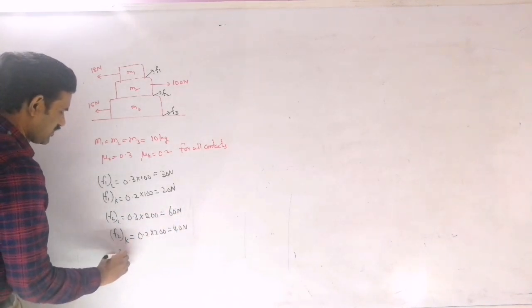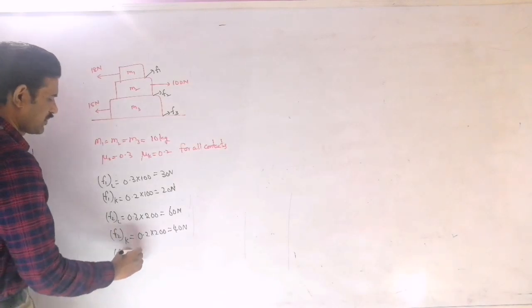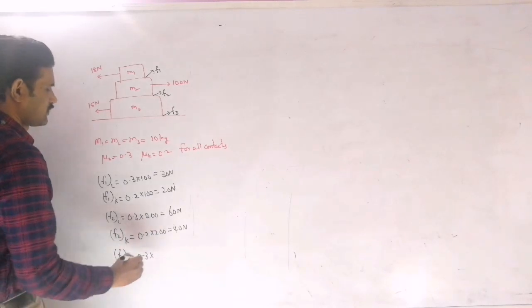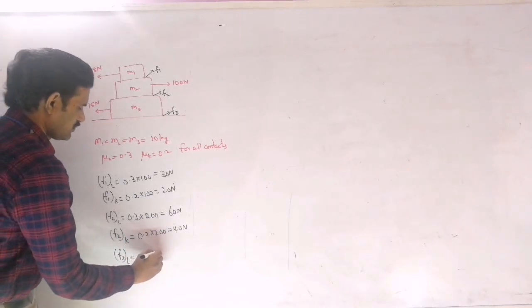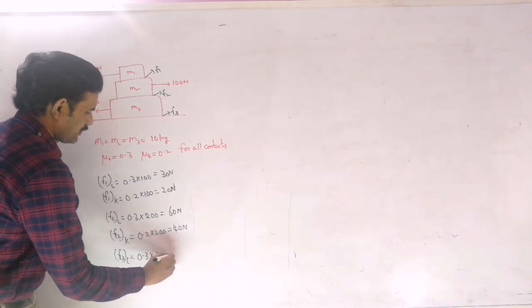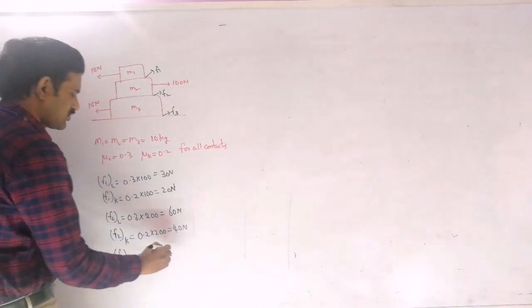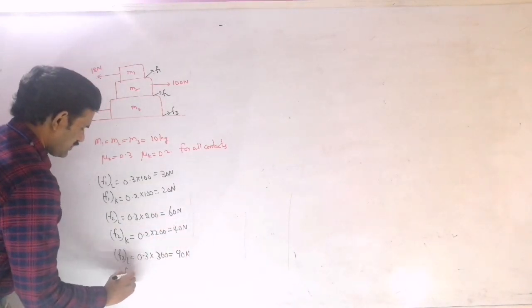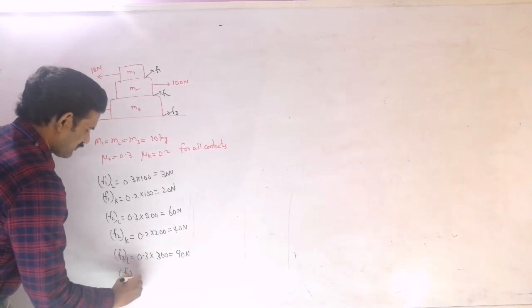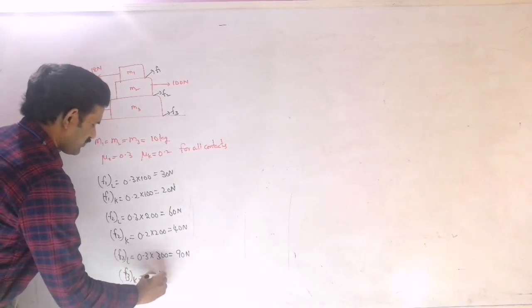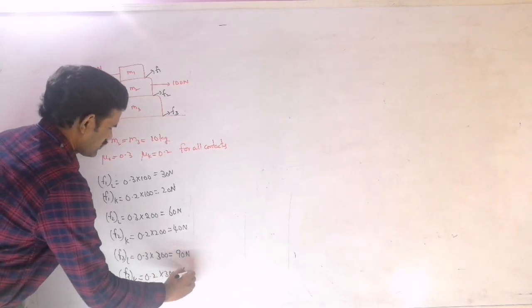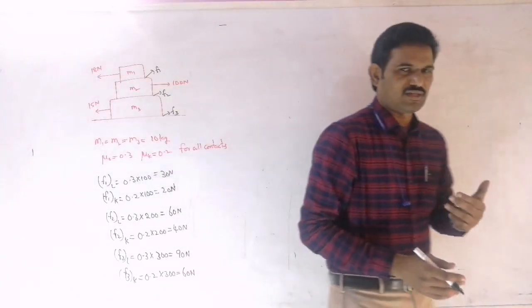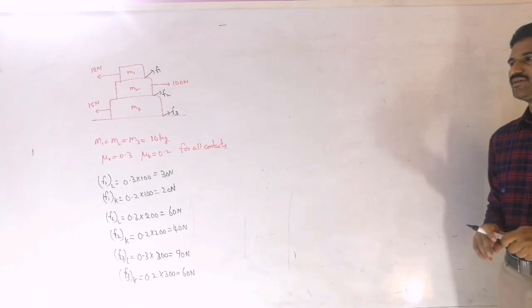And similarly this F3 limiting you can write as 0.3 into 300. Here for the normal reaction, we need to consider the weight of all 3 blocks. So which is 90 newtons, and then F3 kinetic is 0.2 into 300, which is 60 newtons, right? So these are the limiting and kinetic friction values for the different contact surfaces.